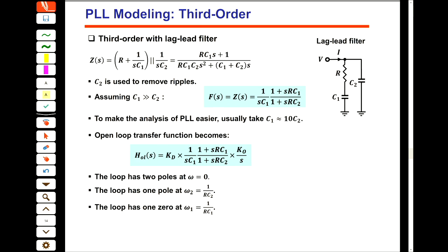So you can just write down a KCL here, and a KVL here. And simply find the KCL here and V divided by I. Got it. No need of Miller, because Miller is not working in this structure. If here is ground, yes, Miller is correct. But when we have a degenerative element, we have to apply KCL here as well as KVL in this loop.